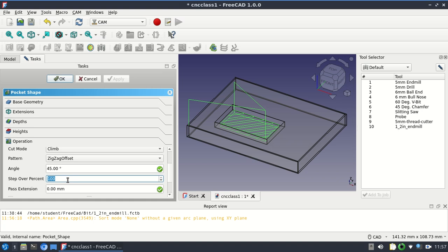How come? So imagine you have some sand, and you put your finger in the sand, and then you push and try to draw a line. You are kind of making a hole, but some of the material, instead of actually being cut, is just being pushed. So usually if you try not to have any overlap, there is a chance that there's gonna be a thin line of material there. So you might wanna change that, depending on what you're cutting.